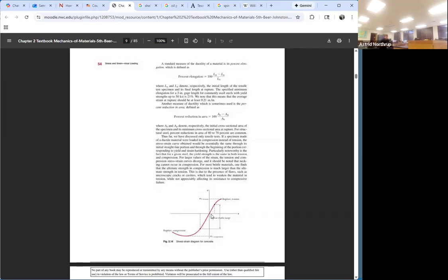So you can see that this is unusual in the sense that you pull on it, it ruptures, and if you push it back together, it has a different kind of curve, but it will eventually rupture in compression. But the rupture in tension occurs at a much lower strain. So if you elongate it a little bit, it ruptures, and you have to compress it or shorten it quite a bit in order to get it to rupture.